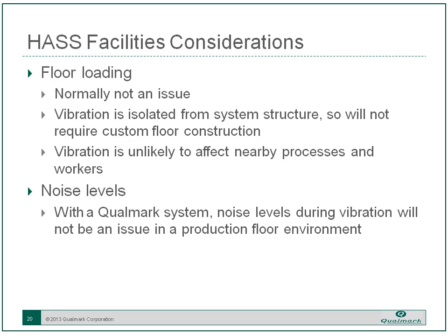Now, one of the things that can happen in HASS is you will have more than one chamber. You're looking at 2, maybe 3 chambers to meet your production needs. And people will worry about floor loading, especially folks who are familiar with electrodynamic shakers, and they're saying all these vibration systems here might be an issue because of the vibration into the floor.